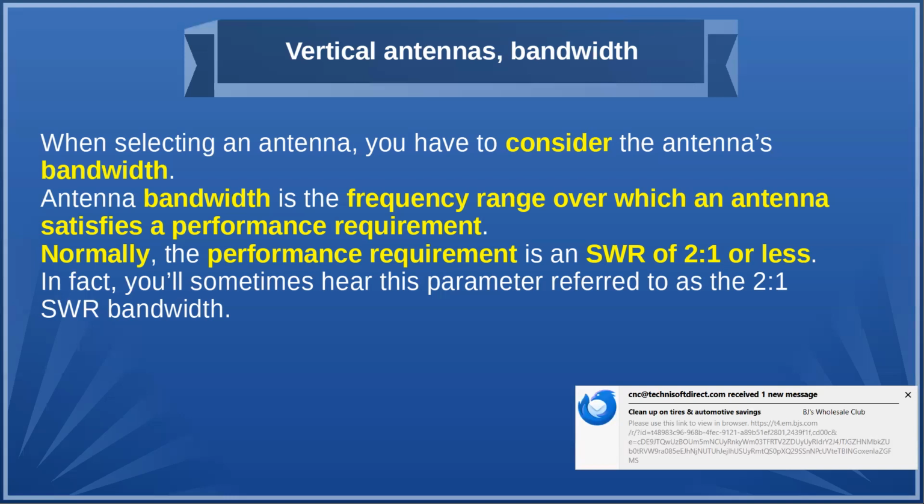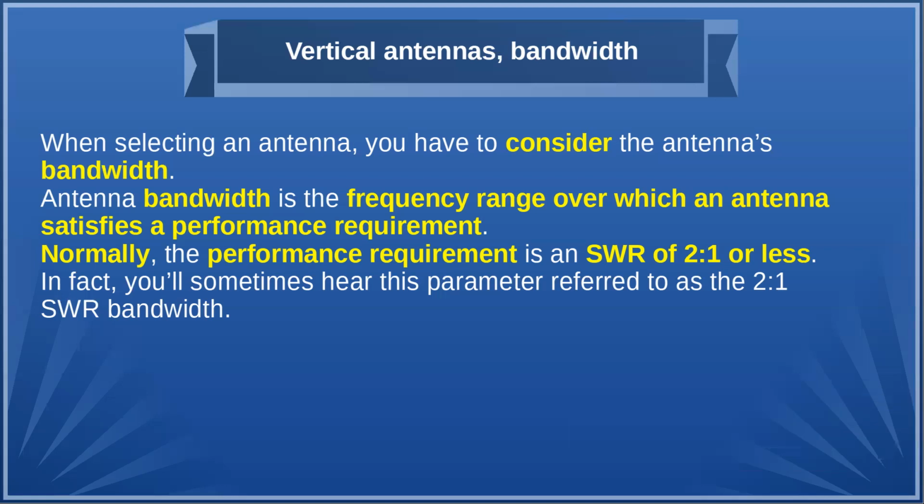I don't know where the tuner name came from, but it's stuck. Everybody calls them antenna tuners. Remote tuners right at the antenna are the best, because this way you don't have loss in your transmission line from standing waves. It's like having an adjustable balun, basically.